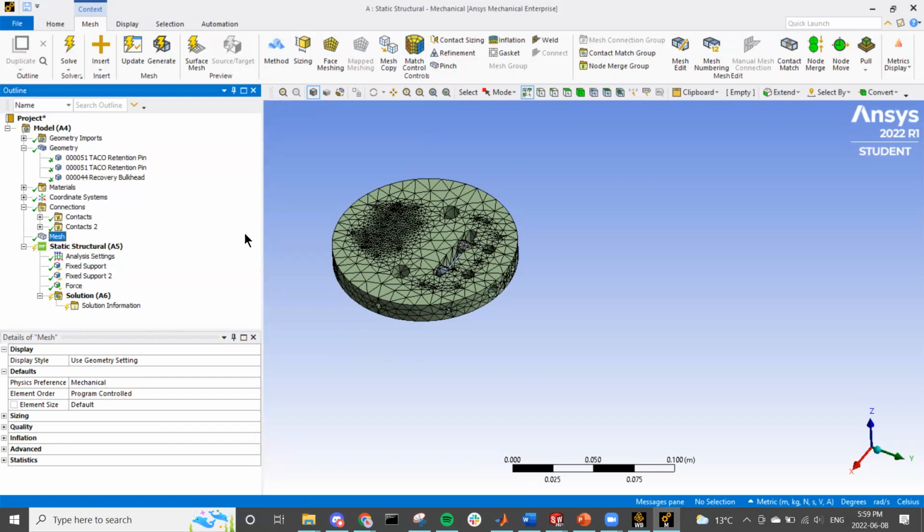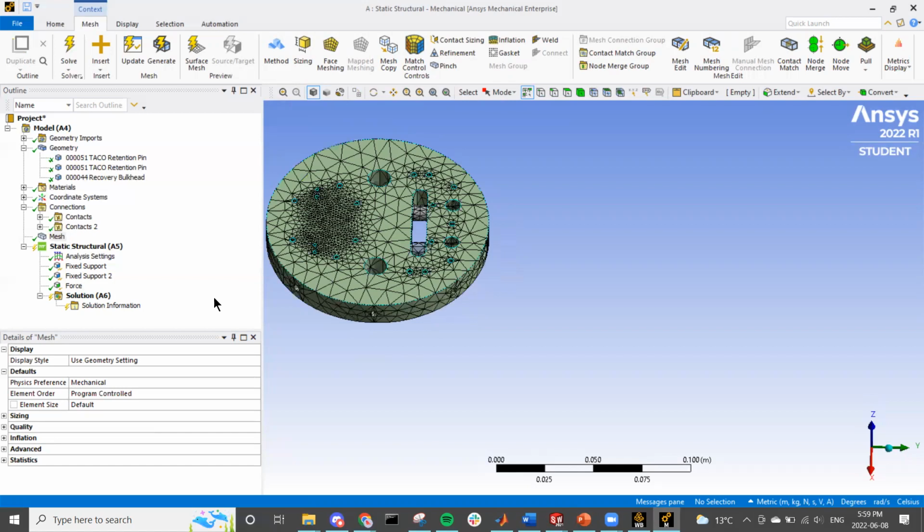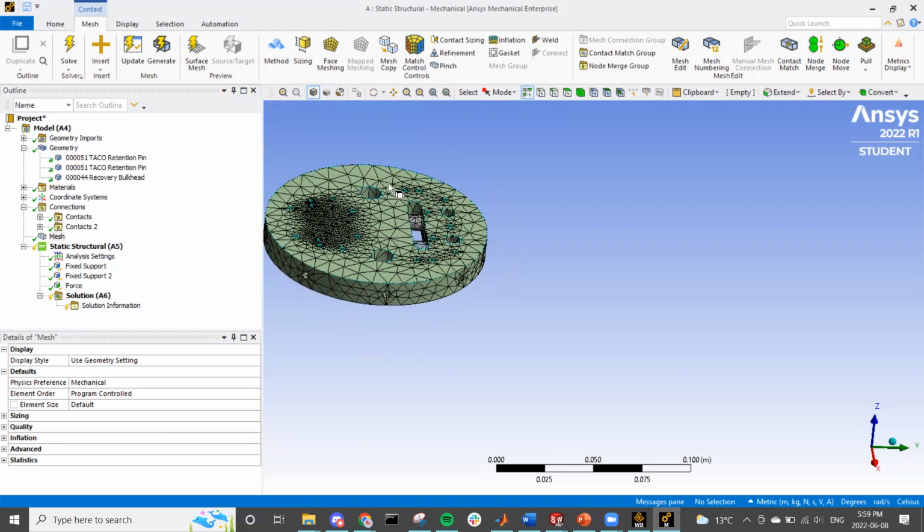And mesh. It's kind of difficult to give you a specific way to do the mesh. But one really good way, if your simulation is not too computationally intensive, is adaptive meshing. Basically you're looking to get your mesh fine enough that it solves the solution, and making the mesh any finer does not change the solution.